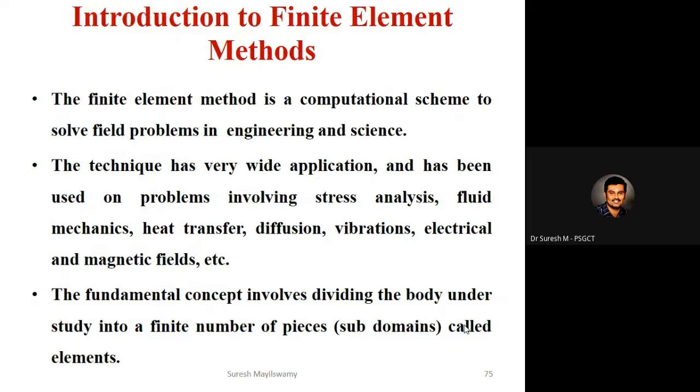So this method is called the finite element method. We are going to divide the entire product into multiple finite elements. Each and every element is considered for the analysis purpose. The finite element method is a computational scheme to solve a field problem in engineering and science. The technique has very wide applications and has been used on problems involving stress analysis, fluid mechanics, heat transfer, diffusion, vibration, electrical and magnetic fields, etc.